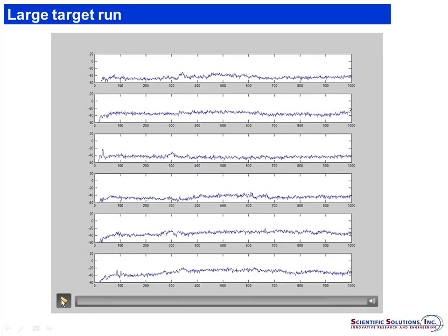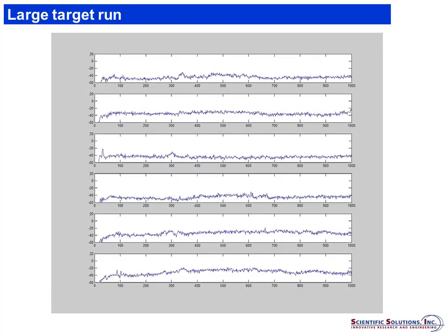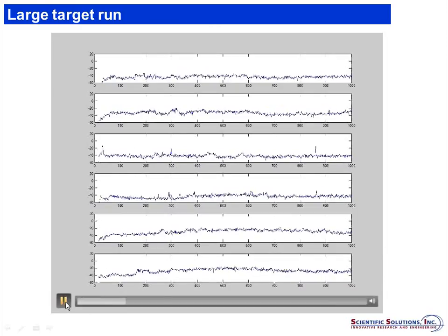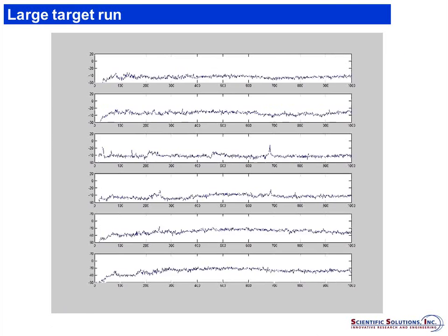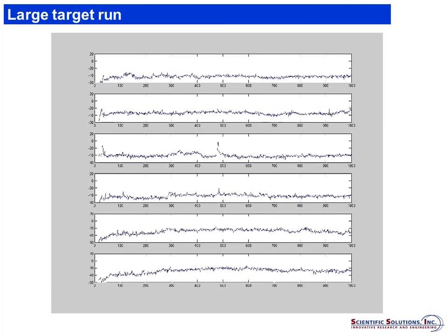This is 6 of the sonar beams, and this is basically return strength as a function of time and mapped into range. So this goes from 0 out to 1,000 meters. If we click this, it's going to play a movie, and the system's pinging at a rate of 1 every second. So as this updates, it's a 1 per second evolution. So you're going to see about a 10-minute run go pretty fast.